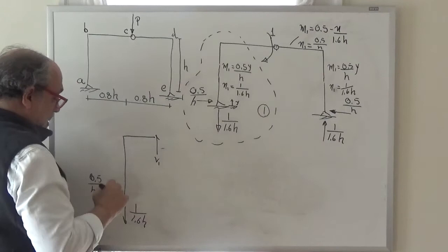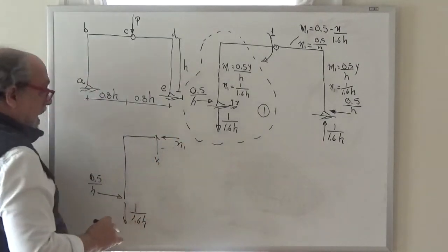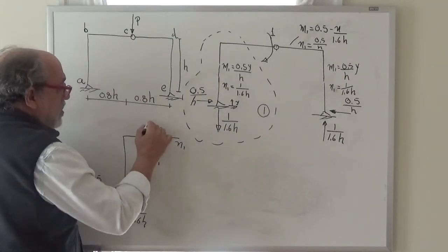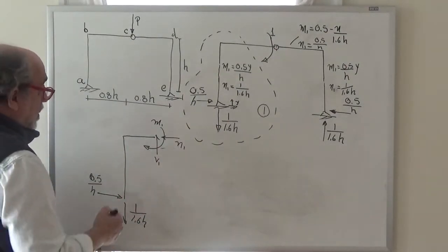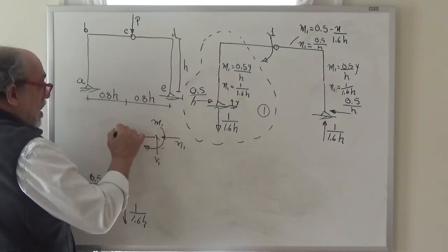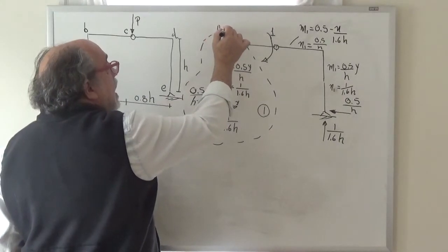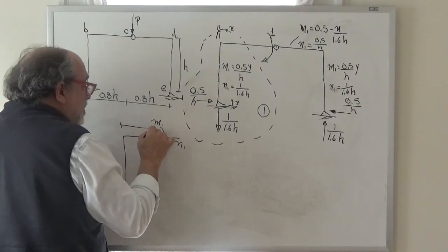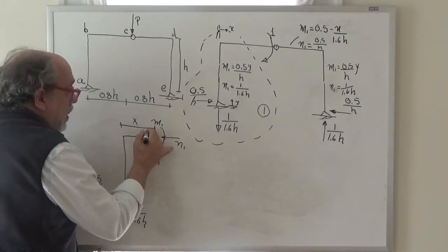So it's going to be my shear V1. This is going to be my axial N1. And I need a moment, which I am going to take to be this direction, M1. Again, just like in the other free body, I realized that I need to talk about distances from here to here. And so I will have a coordinate that starts at this point, and we can call x. And in that context, this distance from here to here is x. This again is our point O.